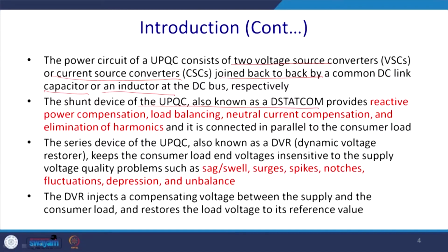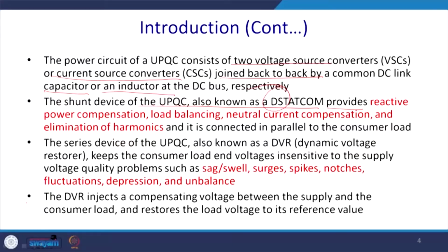respectively. The shunt device of the UPQC is known as the D-STATCOM, because we have studied FACTS where we use the STATCOM, but that is connected at the transmission level, and generally this is connected at the distribution level on the consumer side. For this reason it is called D-STATCOM, or sometimes this part is referred to as the shunt active power filter, which provides all those compensations, that is reactive power compensation and load balancing.